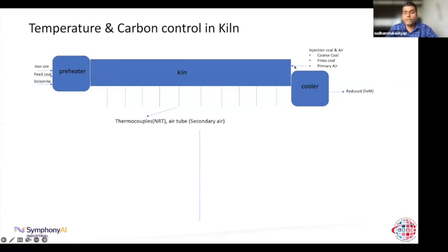And when we are throwing the coal, we also want to ensure that there will be good distribution. So while throwing it, some material falls evenly at the rear end, as well as going through the middle of the kiln. And that's why they put a mixture of coarse coal and fine coal, such that distribution remains even in the second half of the kiln as well.